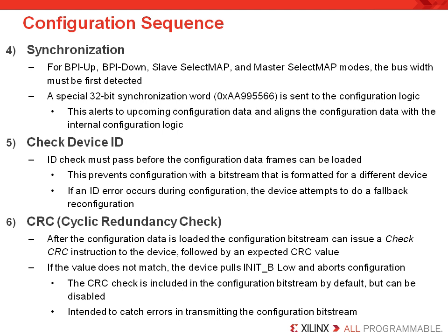This is important because customers frequently have board level or prototype issues that do not allow the bitstream to be transmitted from a flash to the FPGA properly, and they wonder why INIT_B is pulled low. Well, now you know why.